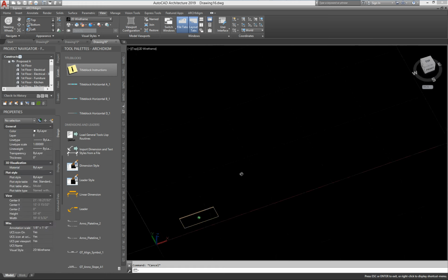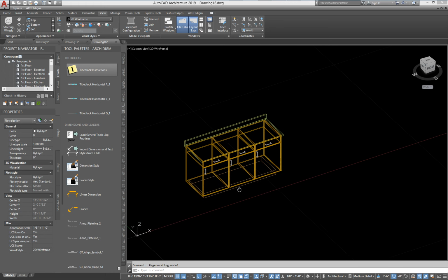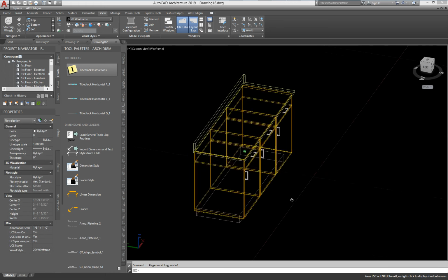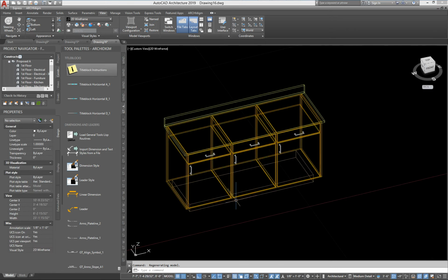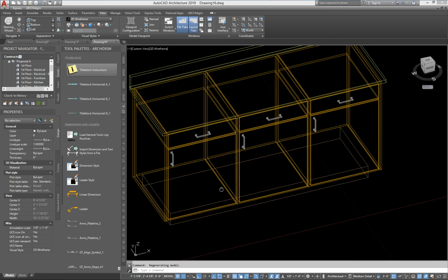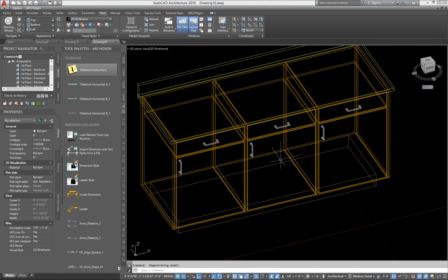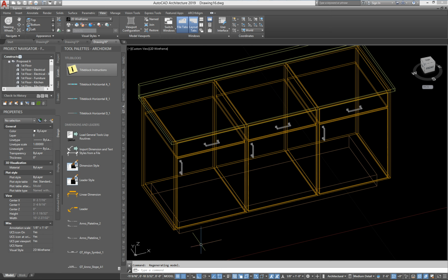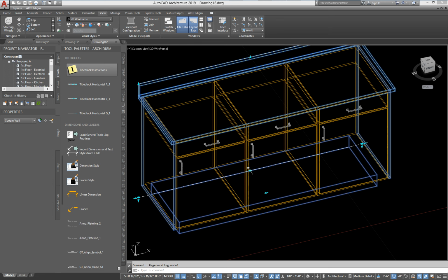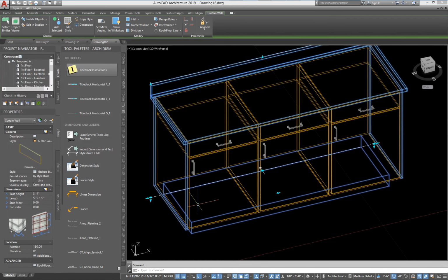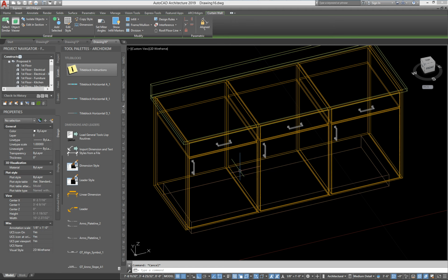If you are working with these, which I have said many times, I pretty much don't use these. If I want to go to the level where I want doors and drawers and all that, I'll use the G3s because I can really control what's going on. The G2s are curtain walls, and they sort of are maybe hampered a little bit by the idea of repetition. So you have this one curtain wall, and curtain walls are designed well for breaking things up into increments. So it all becomes sort of even increments here, right?